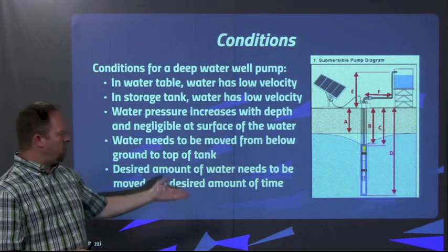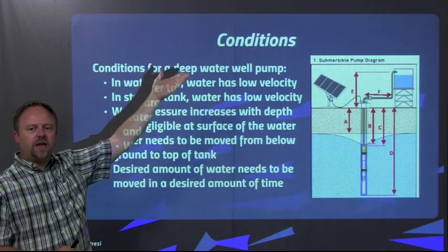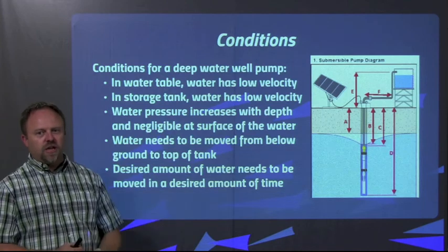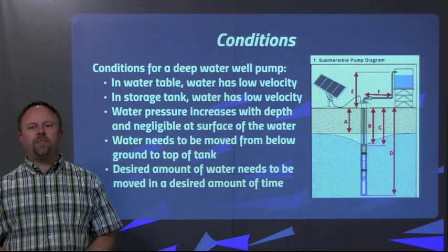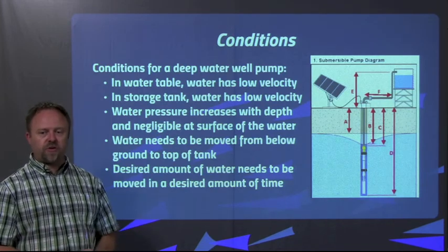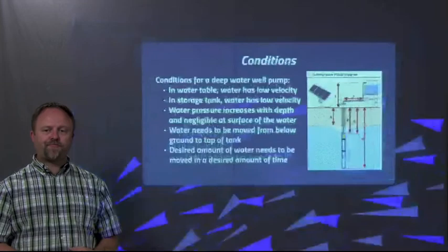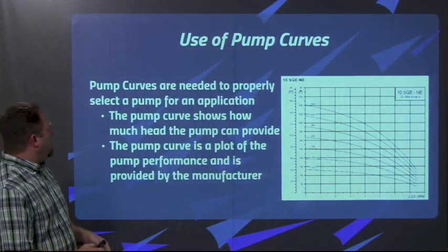And we also need to move the water from a low location underground to a high location at the top of the tank. That's our elevation change. And we need to know also how much water we're going to be pumping in a specific amount of time in order to meet our needs for our community that we're trying to provide water for. And that'll be different for everyone's location.